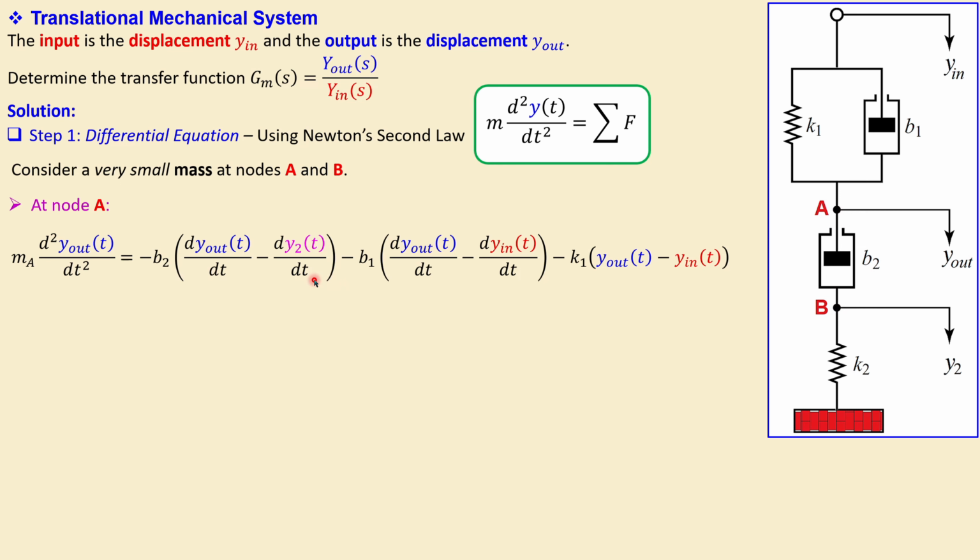That's shown here. That's also the reason why we have this y2 here, to designate that part as a motion. Now for B1 we do a similar thing. Of course, y out and y in are required to determine the difference in the velocity. So it is then minus B1 times the difference: our motion y out minus the velocity at the top, y in.